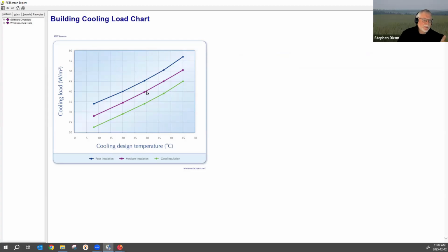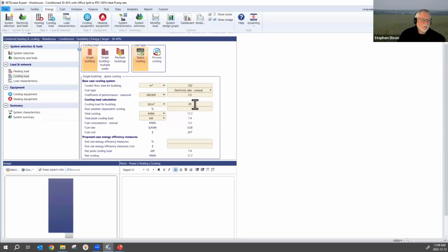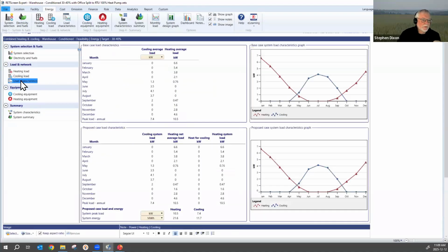And maybe this building doesn't have good windows, okay? Because the insulation takes into account the windows, right? And if these windows have a high solar heat gain, that's going to increase the cooling load. So apparently, the cooling load in this particular building deviates a little bit from what that chart would predict for the heating, but it's likely because of the solar heat gain on those windows not being taken into account. All right. Again, we can do improvement measures, but ultimately it's going to tell us what the load is.